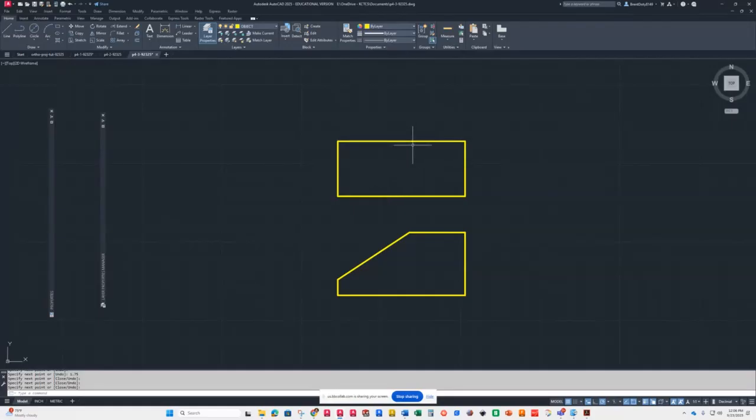Now it says that I've got a line parallel with this top one down 1/2 inch. So we're going to go to offset. Put in 0.5. Offset down. If you did the math, you could figure out that it's 1/2 inch up as well. And enter. Okay, that's all I can do with that one. Well, no, it isn't. I can draw this line up.